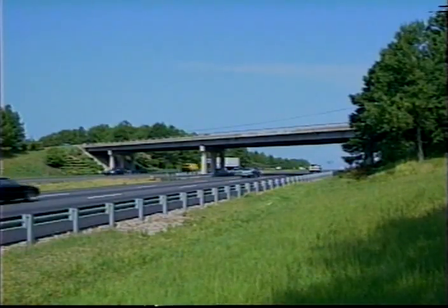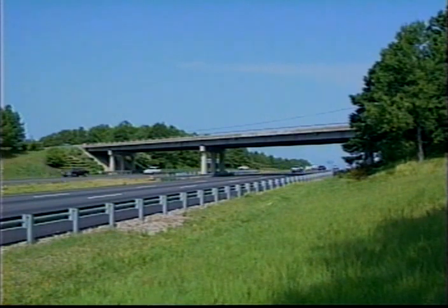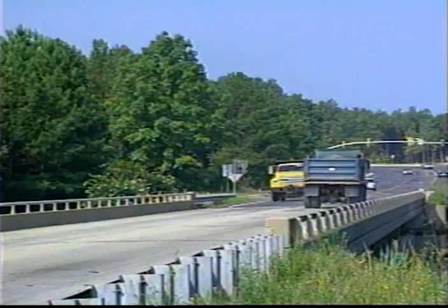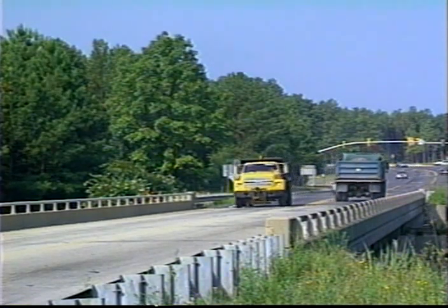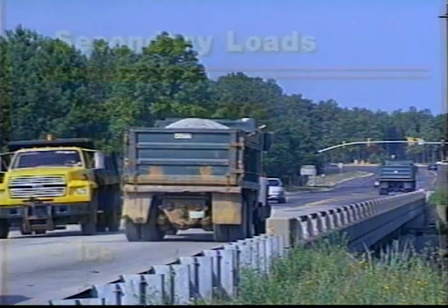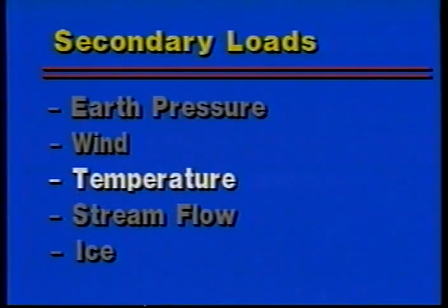Dead loads are forces which act continuously on the bridge, such as the combined weight of all bridge components. Live loads are forces which act intermittently. Live loads consist primarily of the weight of vehicles. Secondary loads include earth pressure, wind, temperature, stream flow, and ice.